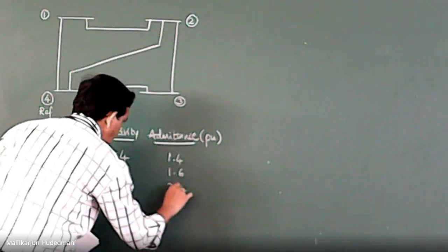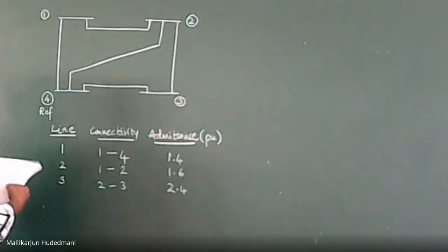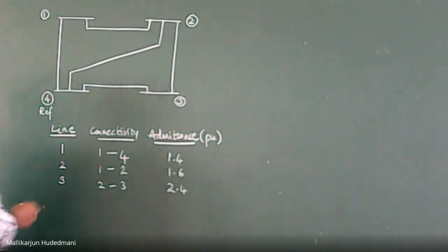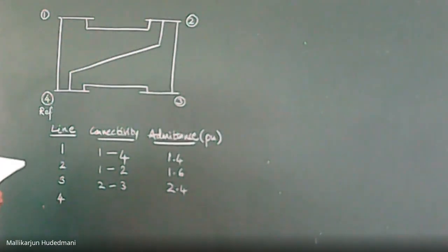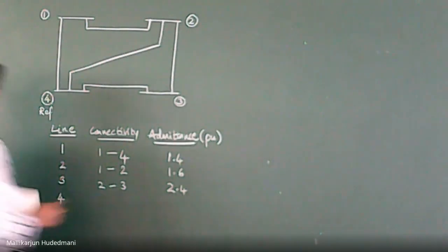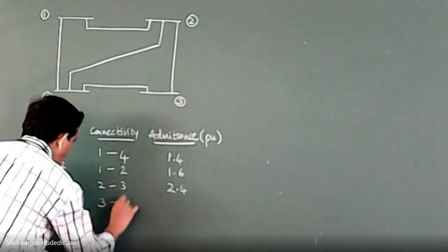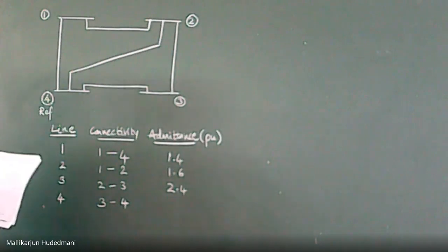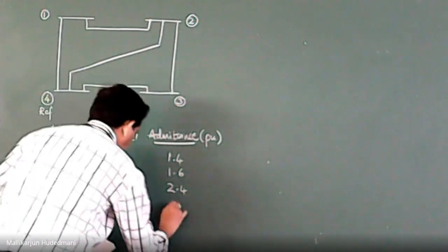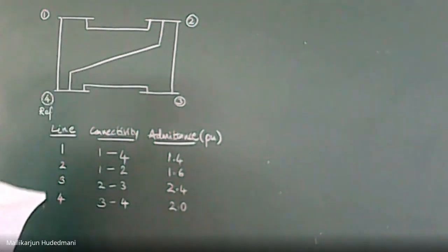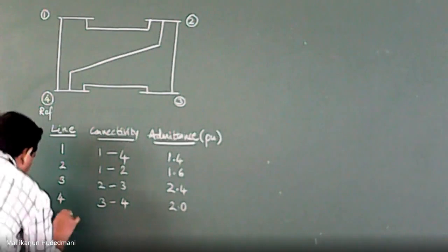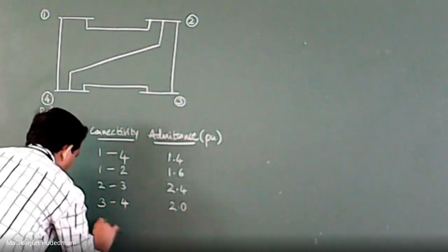This is a very simple problem. Even such a simple problem we will work on in the laboratory using MATLAB: write a MATLAB code to obtain Y bus by singular transformation method for the given problem. You have to generate a program so that it becomes a generic one whenever the content changes, and it should be able to evaluate the Y bus using the principle. Then the fifth element mentioned in this problem is between 2 and 4.